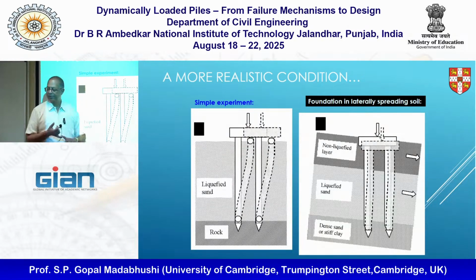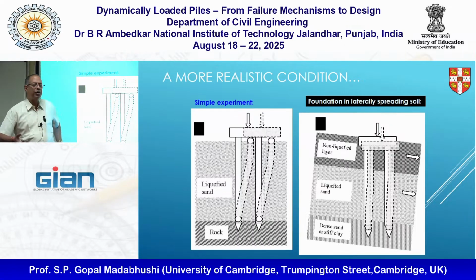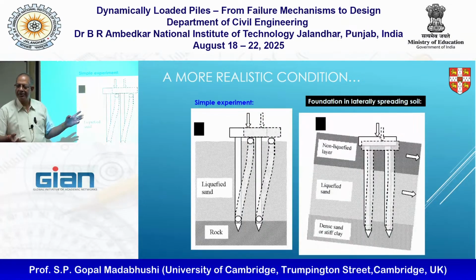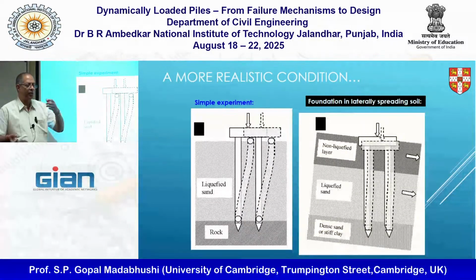So the first thing when you're designing piles, you want to make sure, is do the buckling calculation. Make sure that your buckling load is maybe 7, 8 times larger than the actual load you're going to apply, so that the piles will not buckle. This is the same approach a structural engineer will take when they're designing columns, right? When the columns are being designed, they'll check for the buckling load.